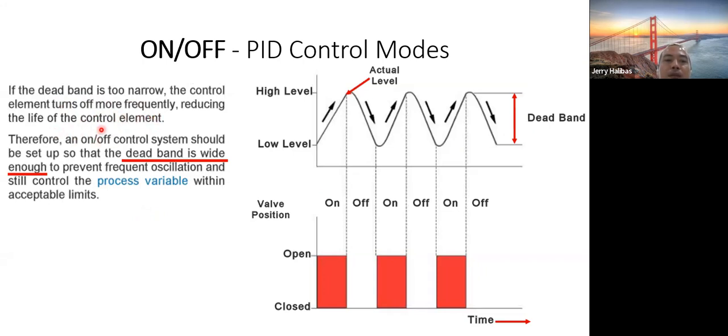This reduces the life of the control element. If it switches too fast, the on-off is mechanical, so in terms of lubrication it will eventually cause problems. Too fast is bad. It is like car engine designs where you preheat your vehicle's motor so the oils can circulate, considering its movements are fast.